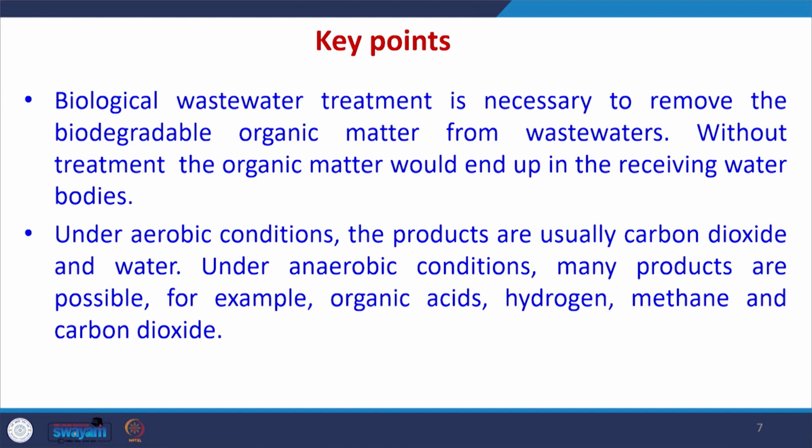So, generally aerobic processes will follow the anaerobic process, so that we can achieve the desired effluent quality. The key point is that biological wastewater treatment is necessary to remove the biodegradable organic compounds from wastewater. Without treatment, the organic matter would end up in the receiving water bodies. So, we have to go for treatment further.